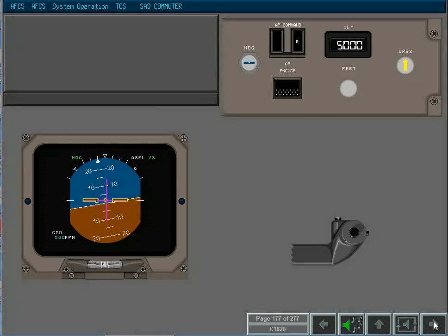On releasing TCS, the autopilot engage light illuminates, indicating that the autopilot servos operate the flight control surfaces. The autopilot maintains the pitch datum commanded by the flight director at the moment of TCS release in vertical speed, IAS, altitude hold, and basic pitch modes. With the autopilot engaged, the aircraft resumes tracking the previously selected heading, VOR, localizer, back course, LNAV, VOR approach, or glide slope.